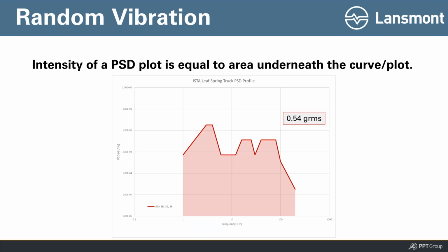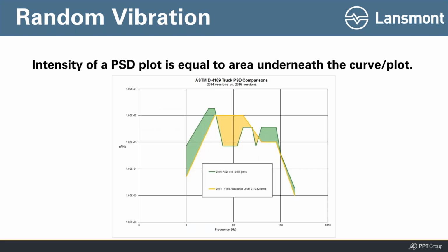And you can think of GRMS once again as being intensity or energy. So higher GRMS, higher energy; lower GRMS, lower energy. Another thing to point out, this is a plot with really two different PSDs overlaid on top of one another. These are basically that same leaf spring truck profile in the green versus the original ASTM truck profile that was probably developed in around 1980 and was updated in the